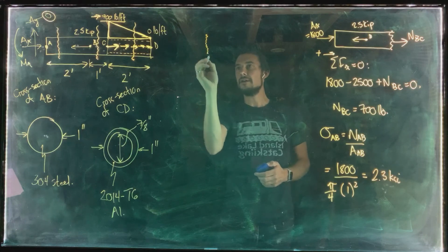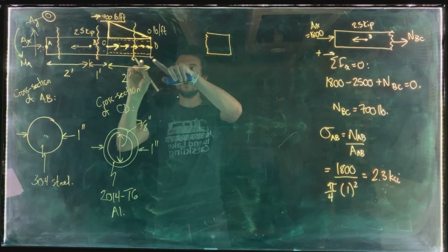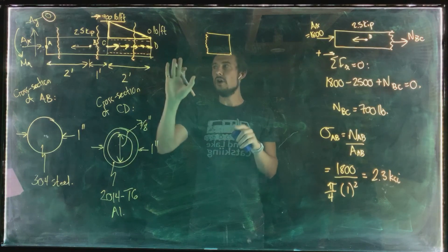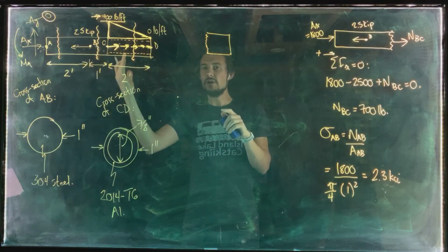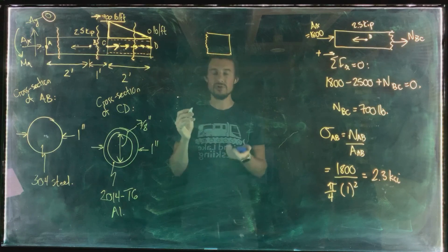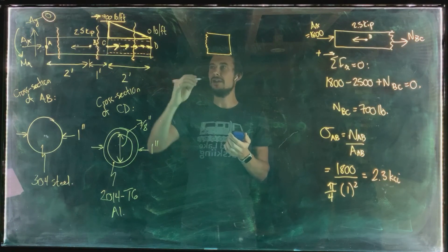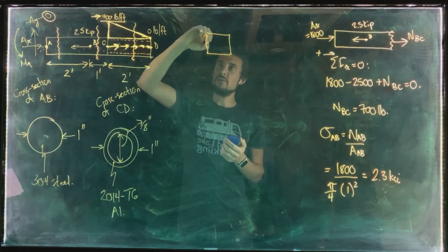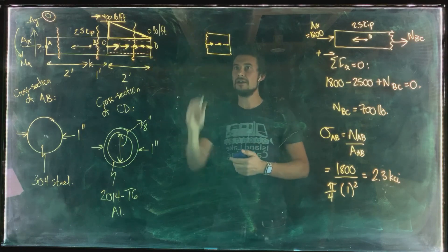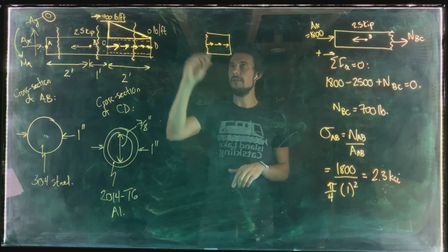Okay, so if we do that, then our free body diagram, if we take the right-hand side of the object, right? Whenever you're finding internal forces, you can always take one portion of the object or the other portion when you do your section cut. And it makes sense to take the portion where there's the least amount of math involved. So here we've just got a little bit of that linearly decreasing axial load present on this.